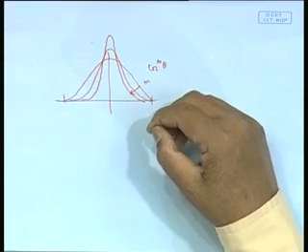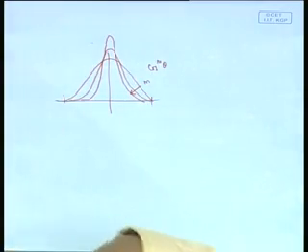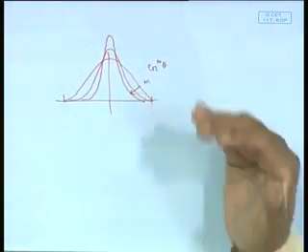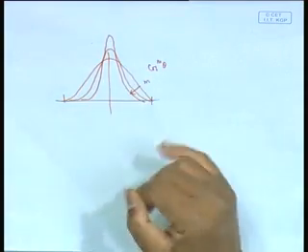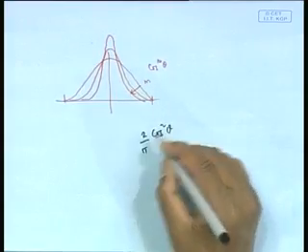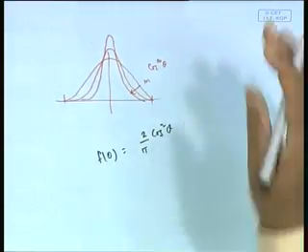Now here is a question of modeling. Let us say that you went to the North Atlantic, and you find that there is a 3-dimensional wave, but the majority of the wave is much more in one direction, with much less spread. So, you would choose a function from literature which is a higher power of cos, more focused. In fact, the larger the m, the more focused the waves, because it is more in one direction. The smaller the m, the more spread. The lowest one that is typically used is 2 by pi cos square. We do not use anything lower than that.